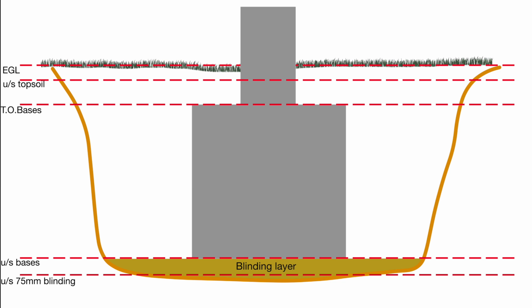Looking at the sketch, we can see there is a lot more excavated volume than the calculated volume, but that doesn't matter. The contractor, when pricing the Bill of Quantities, will take all this into account to allow for all the additional space to get into the excavation to construct it, rebar, formwork and so on. Very importantly, the blinding layer level must be equal to the underside of bases layer level. So although the actual depth of blinding will vary because the excavation base itself will not be that level, it's the top level that must be accurately set to within normal setting out accuracy.